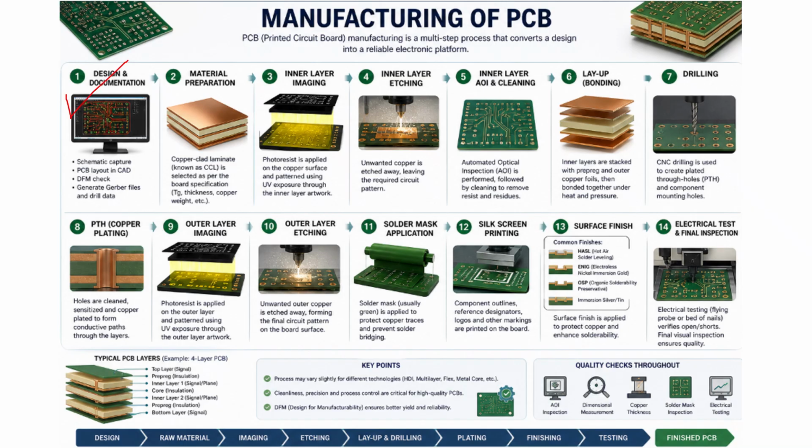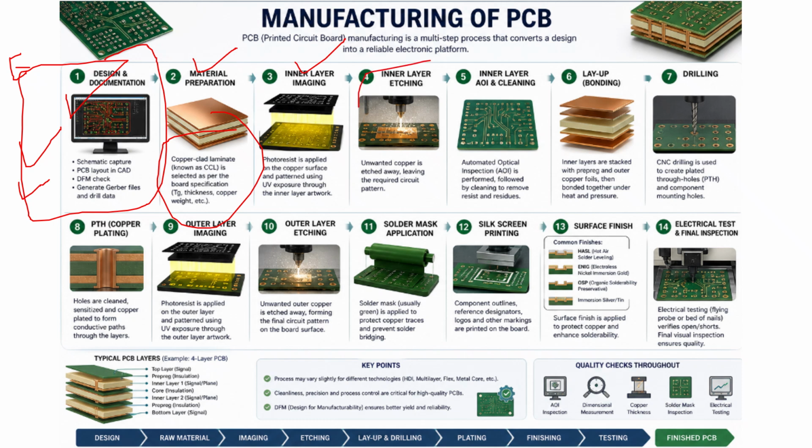So the first thing is design and documentation, which means here you are going to create the CAD file or Gerber file. You can do it using one of the popular software, that is EasyEDA, but that is not limited, right? You can use some other software also. Then the material preparation, like what type of base materials you are going to use, inner layer imaging, and then the inner layer etching process. After transferring the image using the photoresist, you can go to the etching process. Then the inner layer AOI or cleaning process, this is also important.